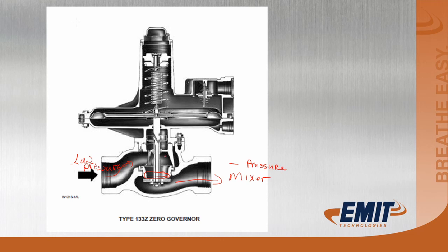Too many guys try to overpressure these and it makes it very unstable. I see a lot of it on the CGs where they're trying to run 10 to 20 psi to carry a load, and then they can't start the unit. Well, that's because that pressure is opening this seat. Weak links on this regulator are this right here.